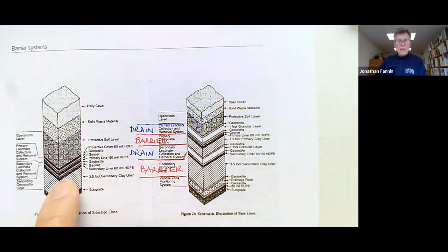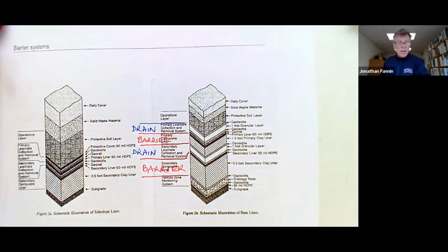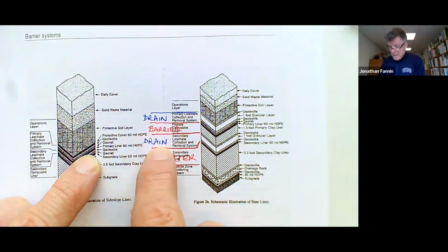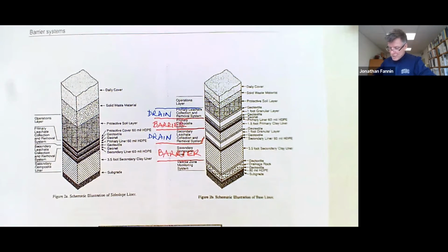And then if we go up the side slopes, and if you think back to the Alouette Dam spillway, you remember we moved to geonets on the side wall, the sloped walls underneath the Alouette spillway panels, because the concern was the ease and quality control on placement and compaction of drainage material, under drains in that case, up the sidewall under the concrete panels. And these are essentially under drains. And when we take them up the sidewall, a similar challenge is encountered.